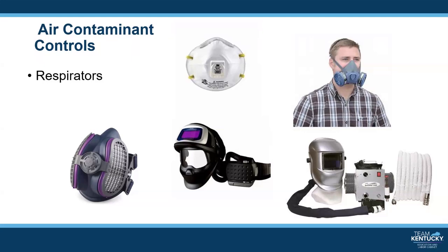This apparatus is the picture in the bottom middle. When welding within a confined space under certain conditions, airline respirators with an air supply hose might be required. If you look at the picture on the bottom right, is an example of that.